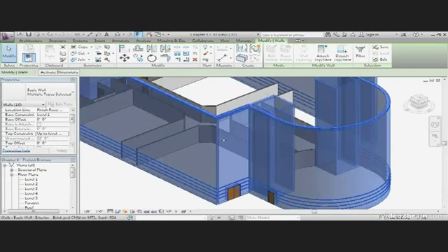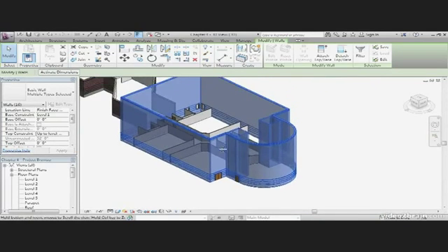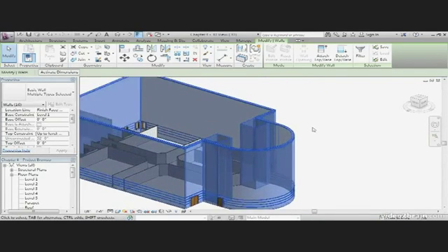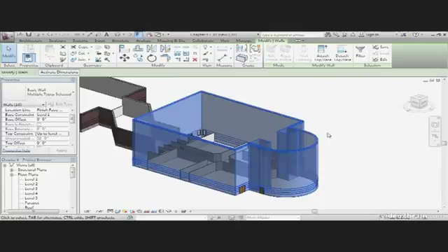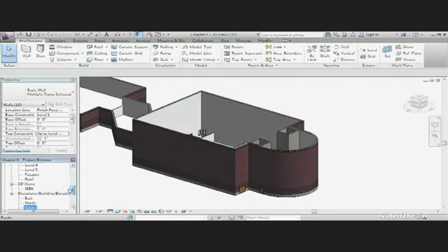Now that we've selected top constraint, parapet, we see that these walls go all the way up to that level. If we change the increment on our parapet to say 60 feet, these walls will suddenly be 60 feet. It looks great, but let's keep going.